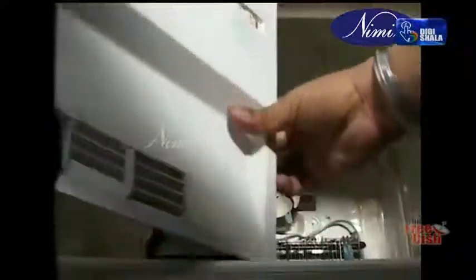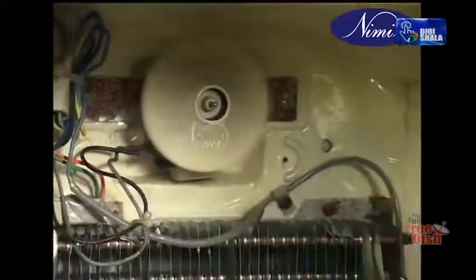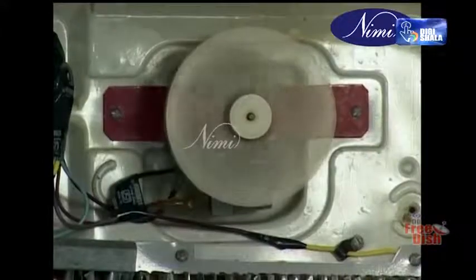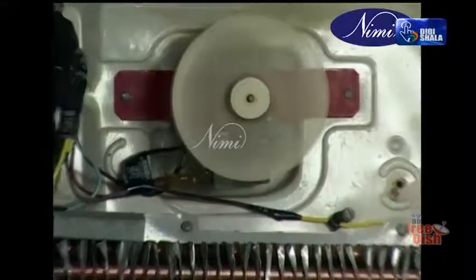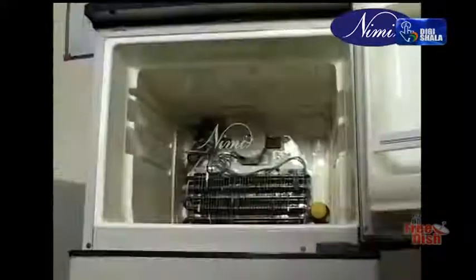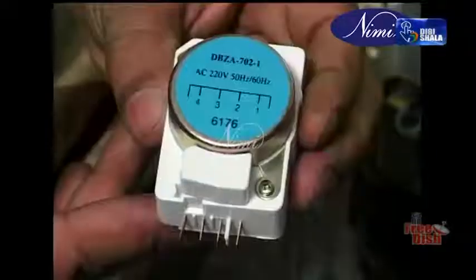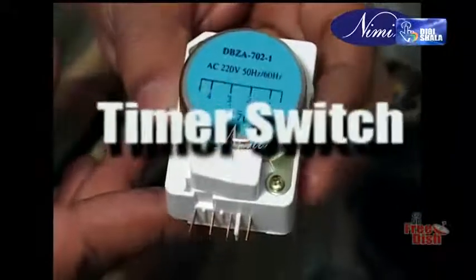The motor is connected with the door switch. When the cabin door is opened, the switch opens the contacts and disconnects the motor. When the door is closed, the contacts start the supply to the motor, which starts rotating the fan and circulates the cool air. The fan motor is installed in front of the cooling coil, tubes and fins type, that is installed in between the walls of the refrigerator.